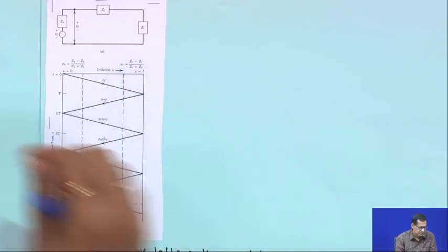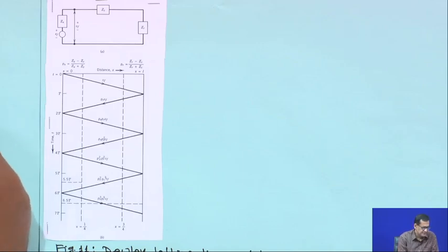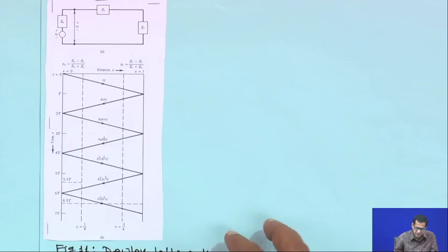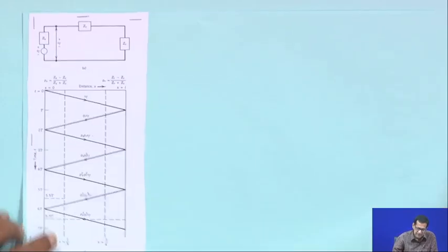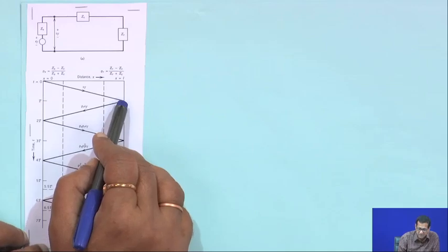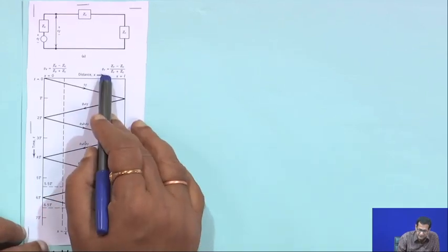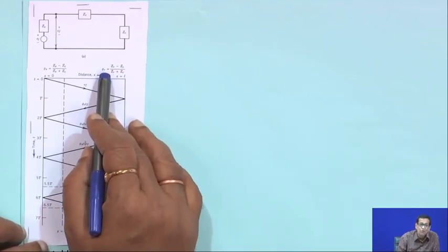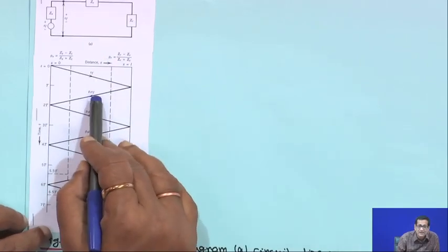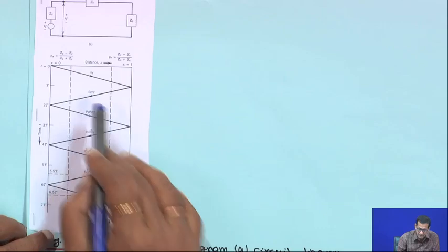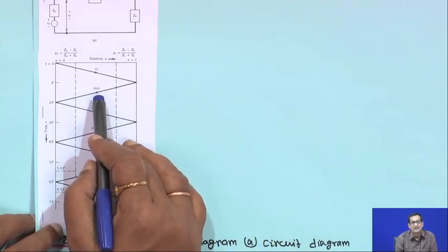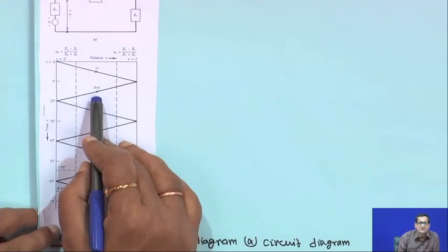We have worked out all the reflection and refraction. So, in this case the travelling wave travels, starting from here, and when it is travelling, it is V f. Now, at the receiving side, the reflection factor is rho r. That means this reflection will be multiplied by rho r, so rho r into V f. The printing is a little bit small, but understandable.